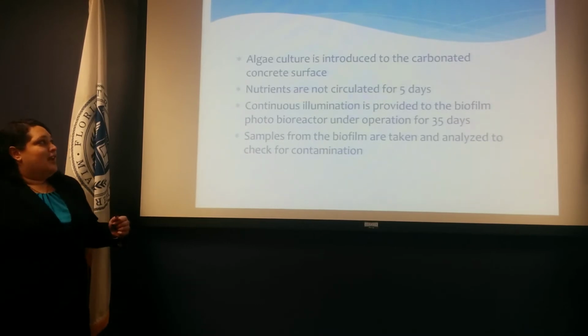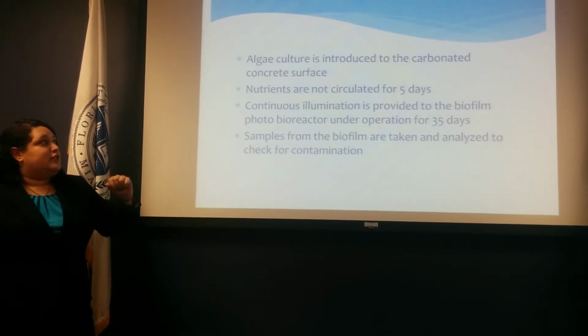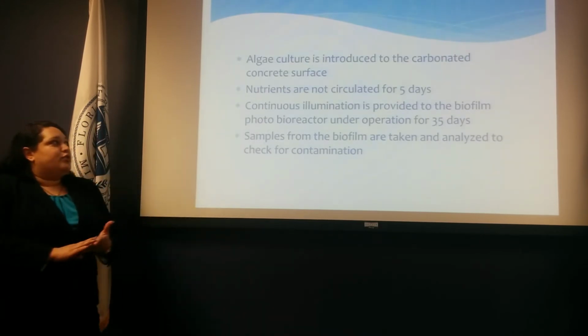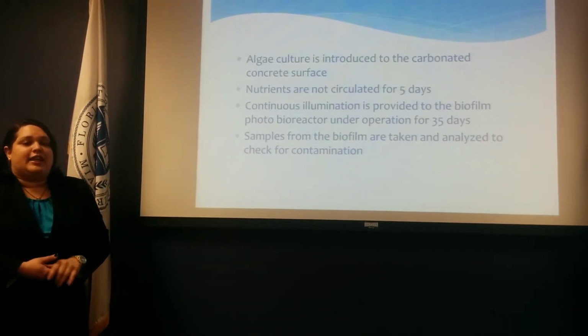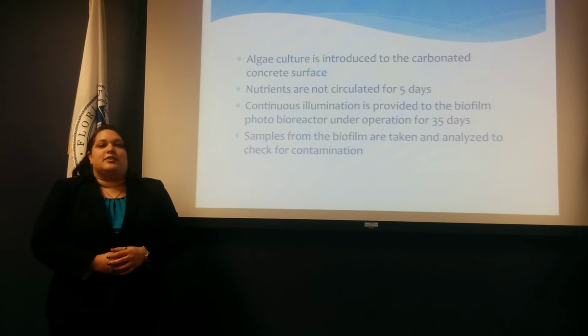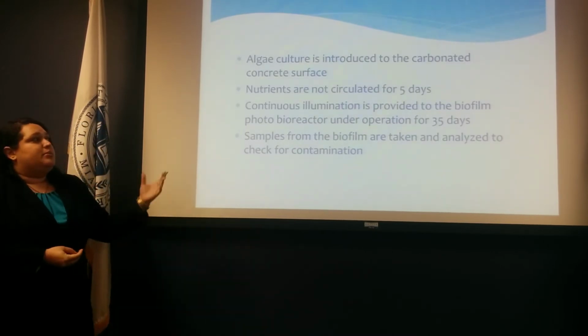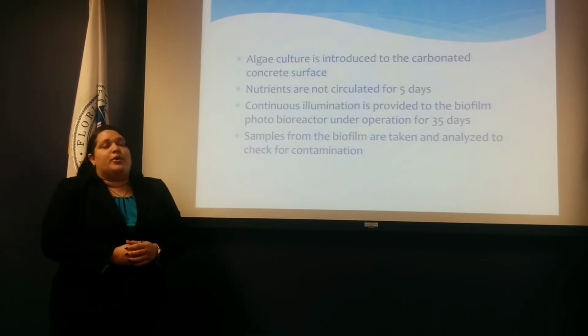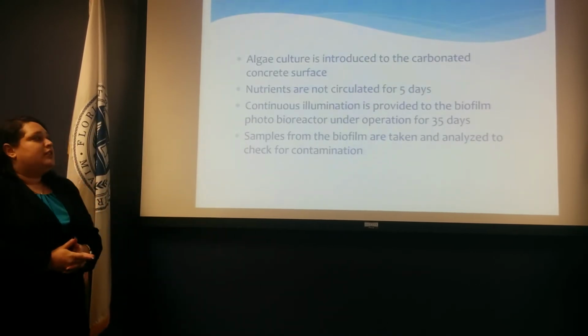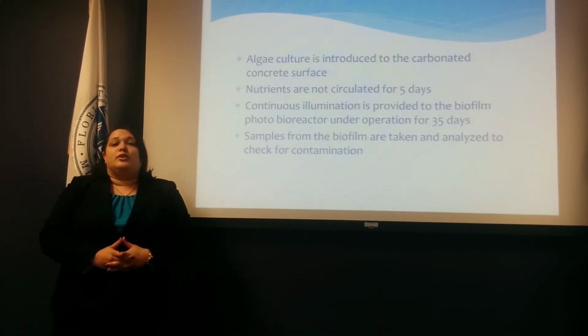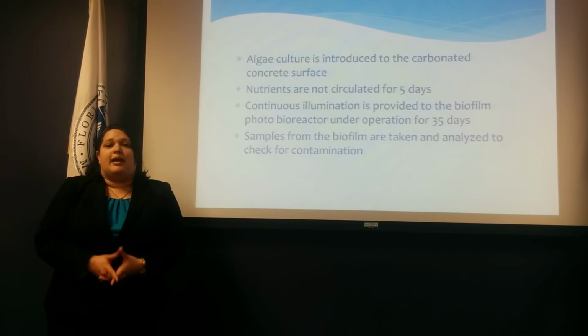Our procedure. The algae culture is introduced onto the carbonated concrete surface, and nutrients are not circulated for 5 days. This is done so that the algae is allowed to adhere to the concrete slab. Continuous illumination is provided to the biofilm photobioreactor under operation for 35 full days. Within these 35 days, samples are taken from the biofilm and tested to ensure that the samples are not contaminated.